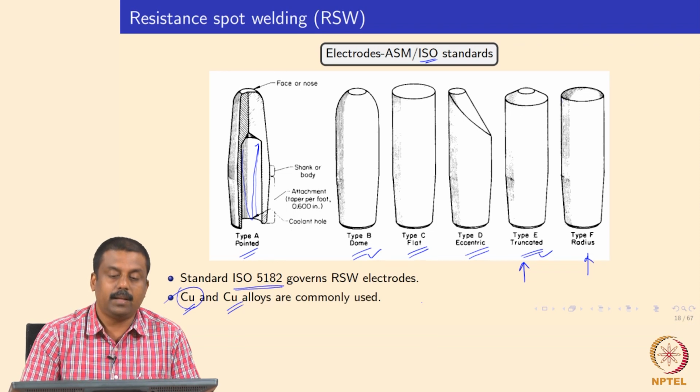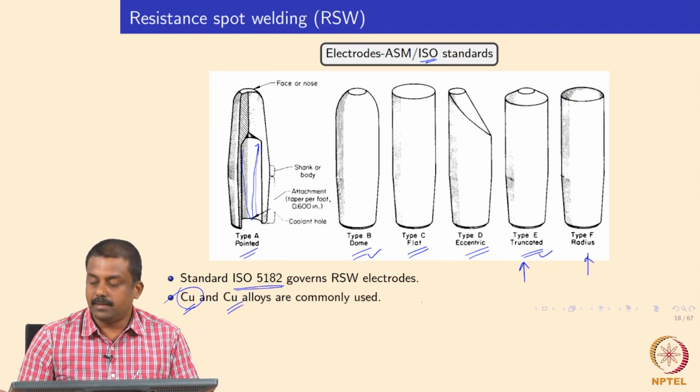To summarize this class, we looked at resistance spot welding equipment and how the enhanced thermal cycle can be used to modify the weld thermal as well as load cycle in our favor. We can introduce a preheating cycle, we can introduce ramping up current, we can modify the heating rate to some extent, and we can also modify the cooling rates by changing the down current after welding.